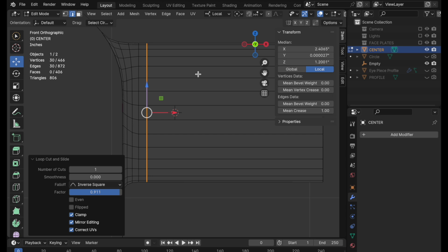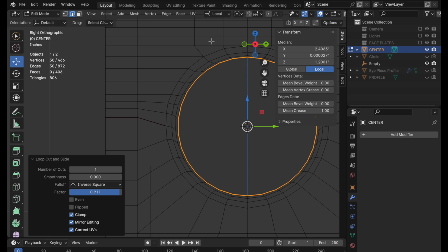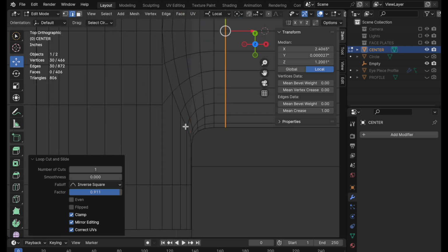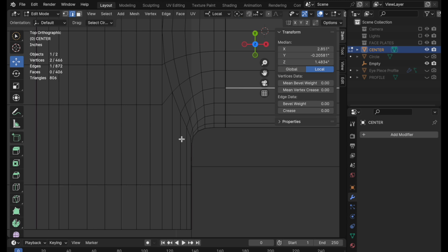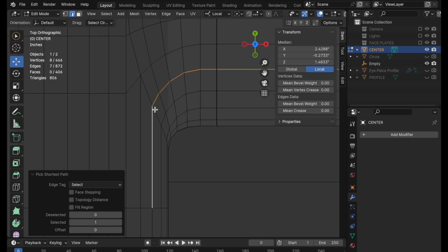progressing past that boundary. If we look at this from the right, we have the same situation where we need to add some boundary loops around here, because if we look at it from the top, we've got essentially flat polygons along one axis coming this way, but we've got curvature coming in. So if we were to look at just this particular loop, we can see that we've got basically the same kind of condition. We need to add a boundary loop around here to really make sure that that curvature is kind of stopping right there and not sort of loosely following all the way in.